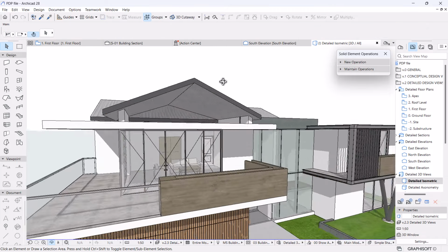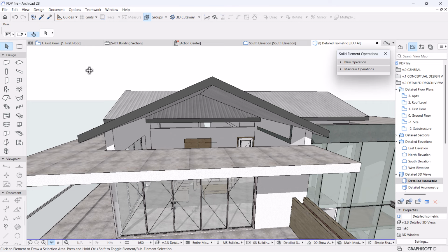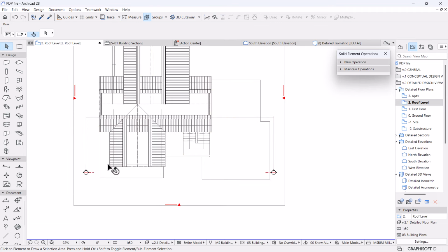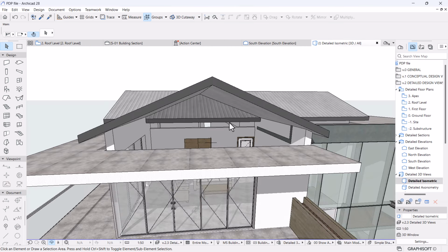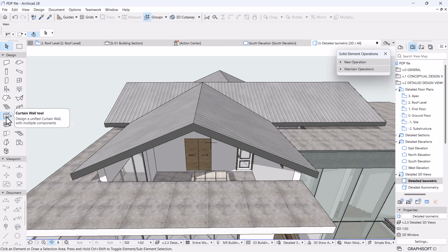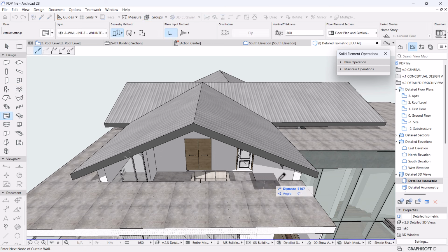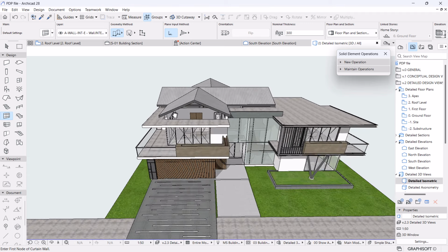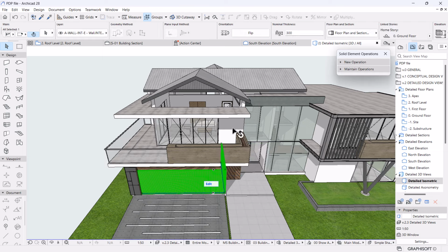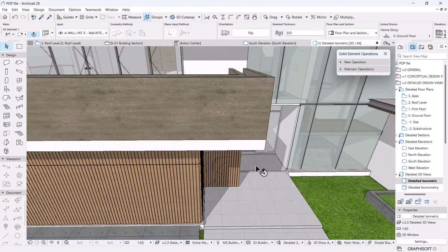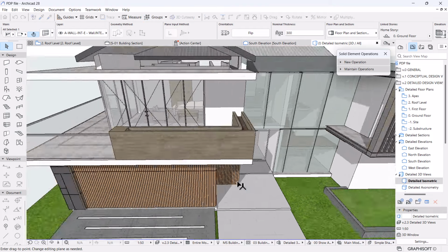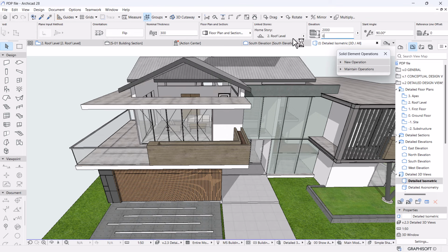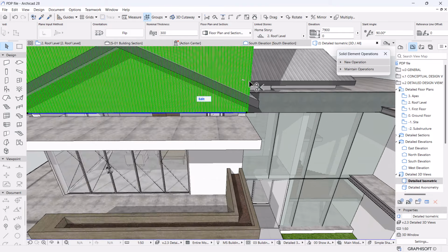And then what I'm going to do is to place a curtain wall here and create that opening. So this would happen on the roof plane. Let's get rid of the trace, and I can also do it in 3D if you don't mind. If you're comfortable, you can do that. So let's activate the curtain wall and set this from there to there. Right click and hit OK. Unfortunately, it's been placed from the ground floor, which is what we don't want. This is the one. Let's set it to be on the roof. You can change the height to be roof, then make it 0, which is the offset from the roof level.